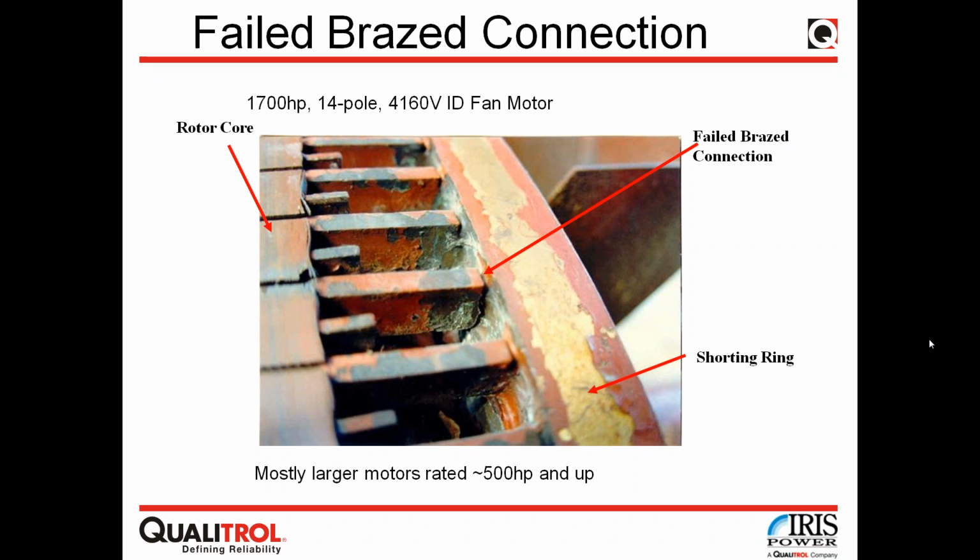That can produce a result indicating the location of the bar that does not conduct the current. However, this will result in a positive identification only on a bar which is broken rather than a bar which is cracked. If there is still electrical conductivity within the bar, this wouldn't be a tool that will help you locate the problem.